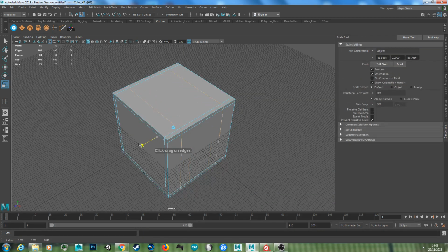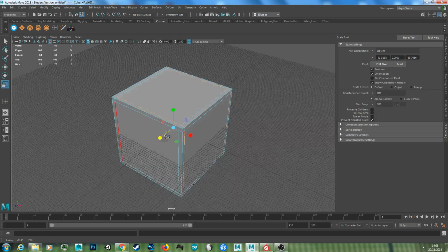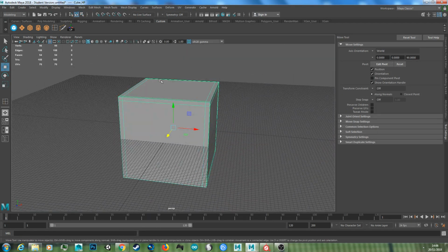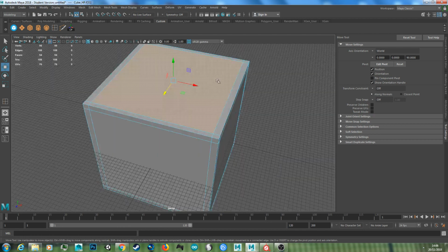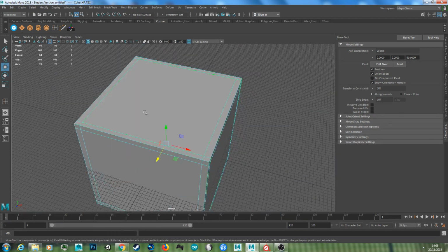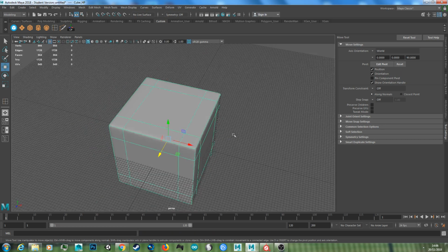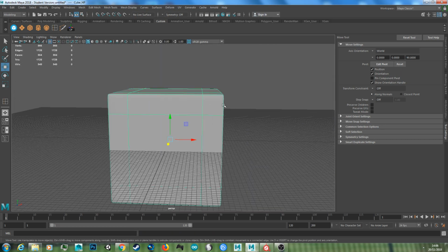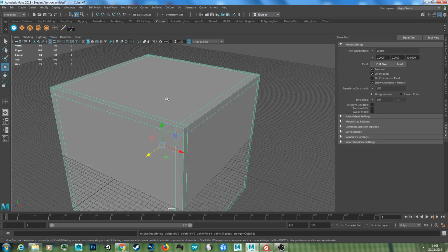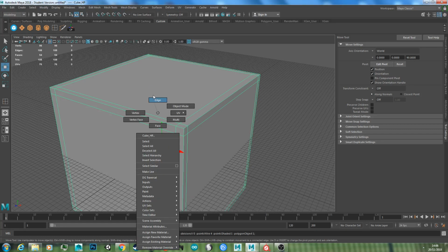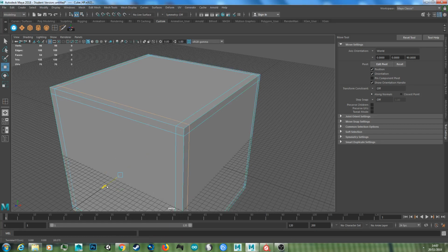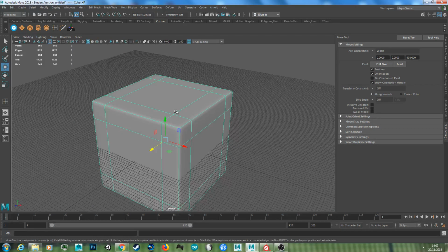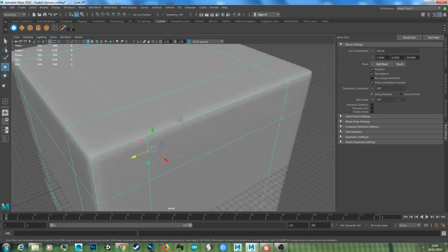If we add some edge loops here, the reason I'm adding the edge loops is so when we smooth the object we get smooth edges. I like doing this rather than bevels, as it gives me extra control on how far the edge is smooth after we've created it, unlike bevel where you have to go back over on yourself.